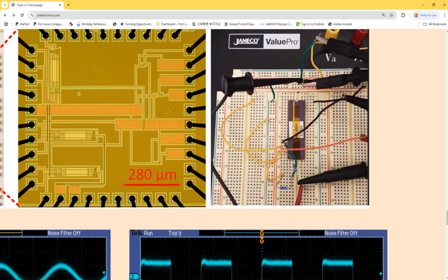So these pads are connected internally inside this ceramic material, which is a package of the chip. And all these pads inside are shorted to every single pin, the 40 dip pins of this chip. So there are 40 dip pins, starting from the little dot here, which is pin 1 usually. If you pay attention to this one, it has a little notch on the top, and that indicates the orientation, which is the top.